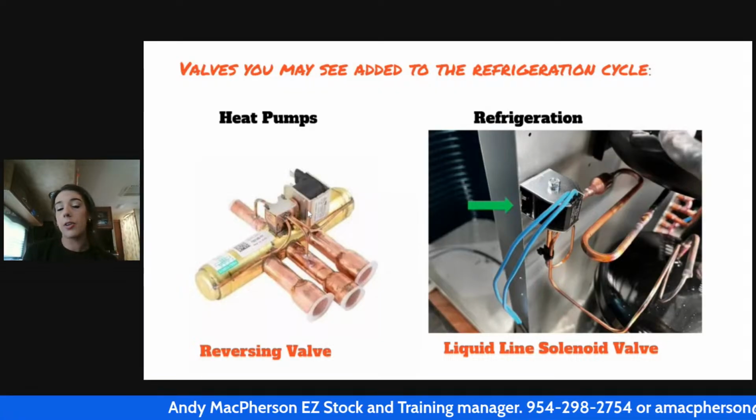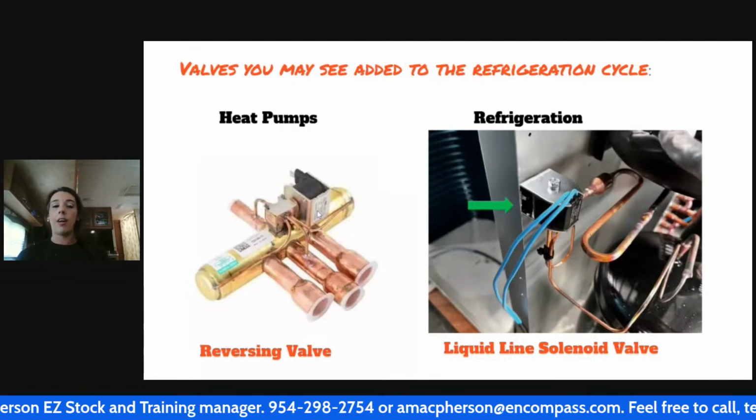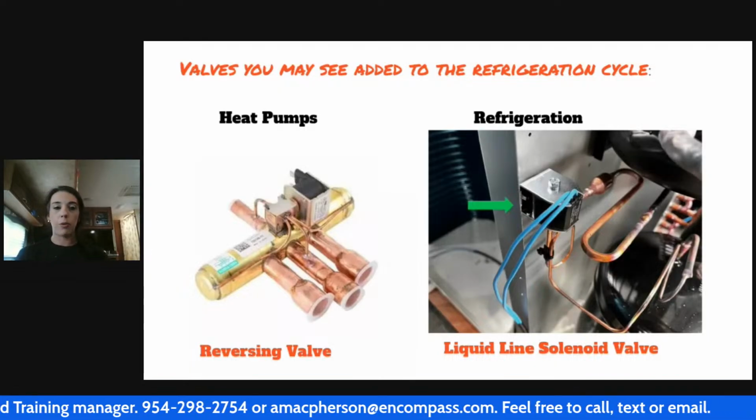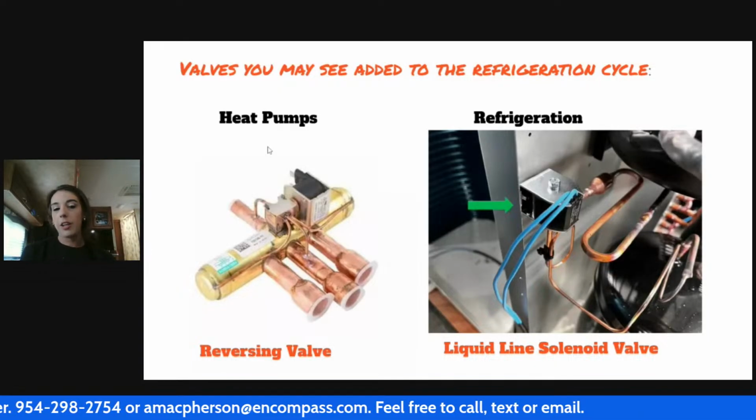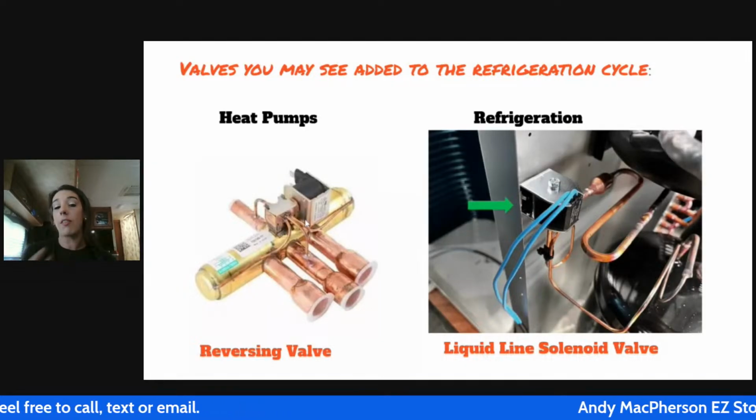And what it's going to do when it's talking to it is, the thermostat's going to say, hey, homeowner just switched this into heat. We need to change the direction of flow. So it's going to slide from here. It's going to slide the internal valve body over in order to allow that flow out of the correct pipe.